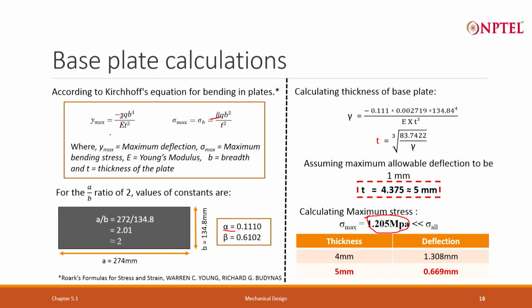But sometimes we may not like to go for a thick material up to 5 mm. No. How can we reduce? Is there any way? Yes, we can do it without increasing much weight and volume. In that case, what can we do? What we can do is provide ribs, we can provide stiffeners. It is like a beam you are providing. It would look like,